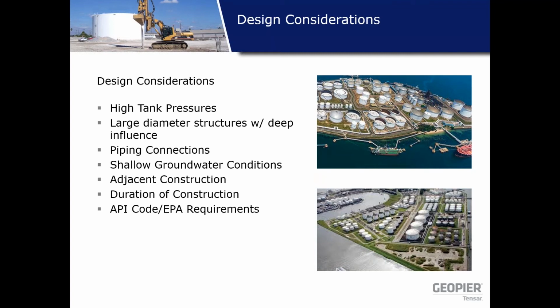API code and EPA requirements. Due to the nature of the material stored, these are critical structures, and we need to study the containment area. Sometimes these tanks are double wall tanks, or they have some containment berms, and we need to consider this in the design.